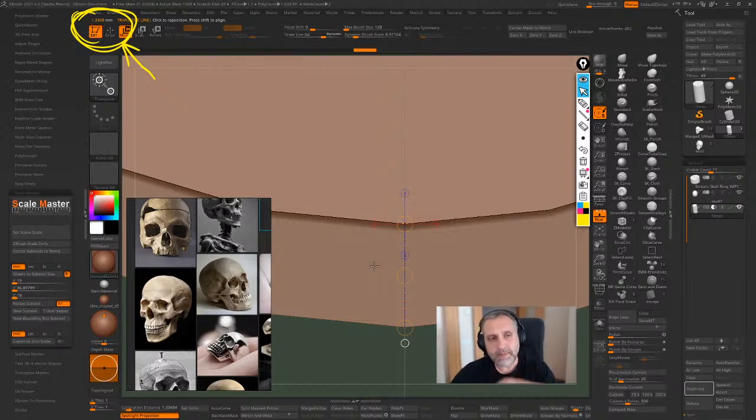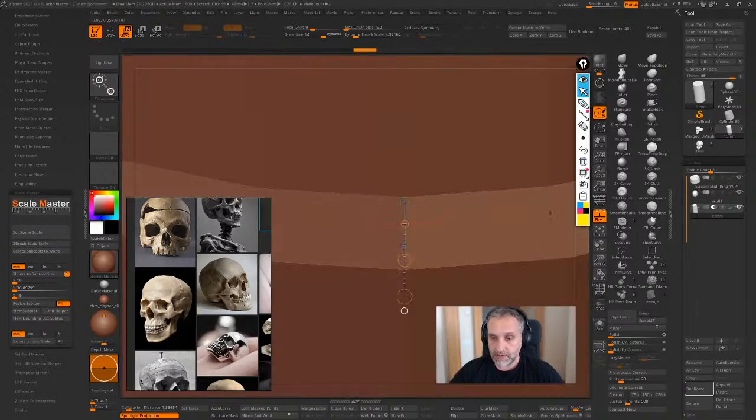Maybe we can try to reach at least 3 millimeters, more or less, to have enough material to start sculpting the surface, because during the sculpting process we are going to lose half a millimeter or maybe more, 0.6, 0.7 millimeter, depending on the kind of surface detail we need to make. So for the first decision, let's try to make it thicker, because we know that we are going to modify it. We're going to make it thinner during the process. So let's make it bigger.